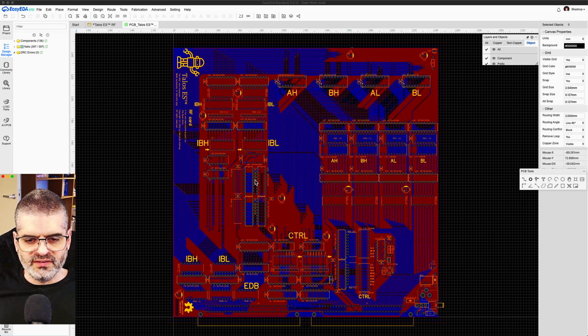So these just drive the high value of the local bus into the local bus, and that value will come either from A high or B high or none if you're not driving the local bus through these buffers. And this is the same for the low part. These 2 buffers will drive either A low or B low or neither to the low byte of the local bus via the resistor network of 33 ohm resistors.